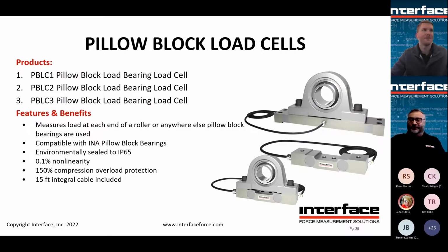Pillow block load cells. This is a product where the load cell is designed specifically to mount to a common pillow block bearing, INA pillow blocks. So imagine if you have rolls or rollers, something where you have product that might want to be weighed on those rollers, you could mount the roller bearings straight to the load cell. Also for things with rolls, monitoring roll tension and pressing, like on a steel roller where they're actually pressing two rolls together, these kinds of load cells are useful for things like that as well. Next slide, please.